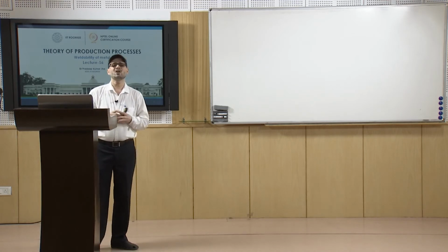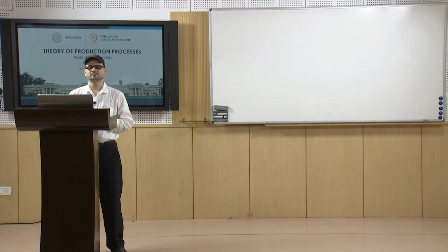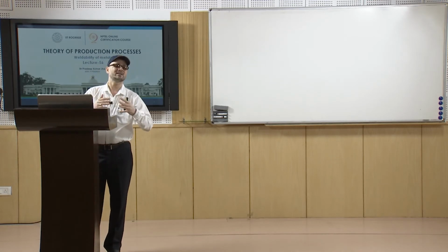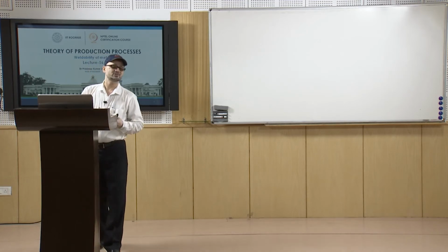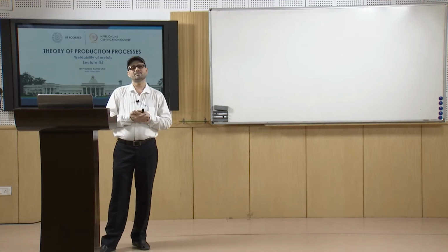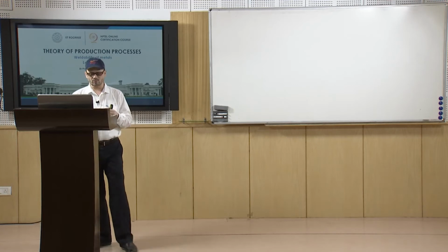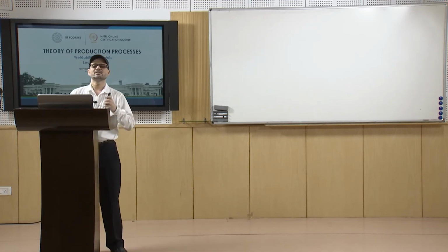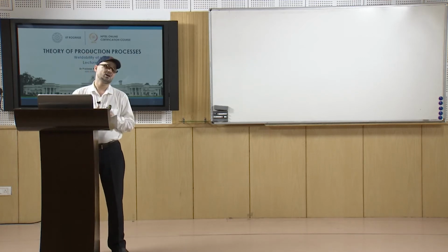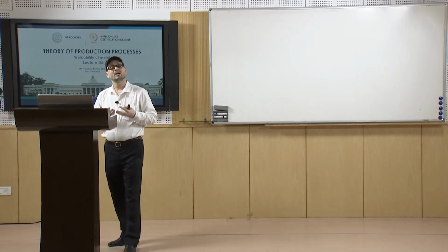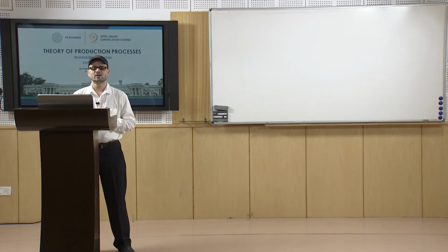So, in a nutshell, when we talk about the weldability of a material, if the material has adequate weldability, we must be in a position to tell with confidence that the material's strength and toughness should be quite high after welding. These are the challenges in welding. When you do the welding and if the heat extraction rate is too fast, hardness may increase but toughness may go down. So, what you aim for after welding is that you must have the proper strength and toughness even after the welding. Similarly, even with high dilution, you should be able to give a good quality of weld. That is another requirement for a material to be good weldable.